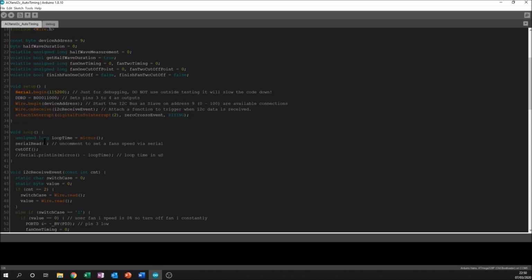If I was to show you how quickly this loops, I'd expect it to be 4 microseconds, and to that extent we could actually have about 500 unique fan speeds, potentially even 1,000, but I'd account for the first loop and then setting in the second loop, because again we need 2 interrupts, so really 500 different fan speeds. But let's have a look how quickly it loops.